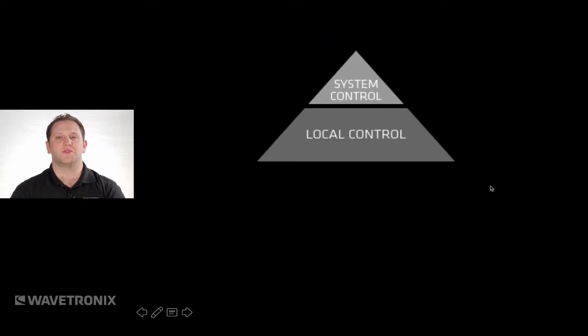One of the things that we hear most frequently is good local control. Local control in an intersection means that the intersection is working well on an intersection by intersection basis. It also means that engineers are trusting their timing plans, that the equipment is properly detecting, that it's properly preempting, that splits aren't too long or too short, and traffic is flowing well. But there are two giant hurdles to getting there that the SmartSensor Matrix, which is a product we'll be talking about today, helps with.